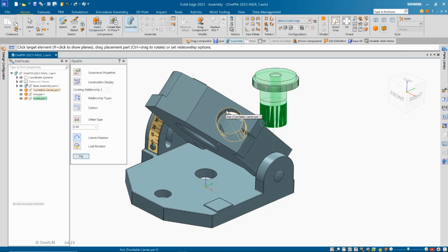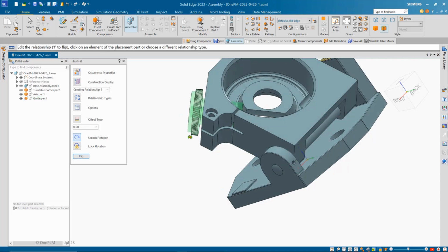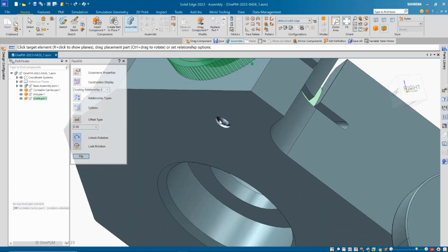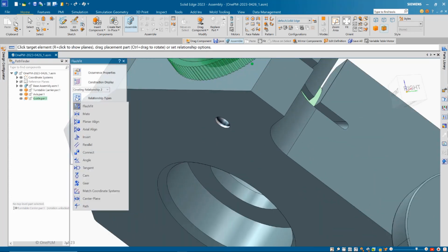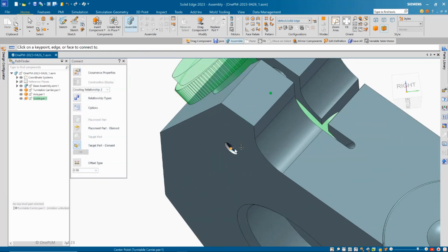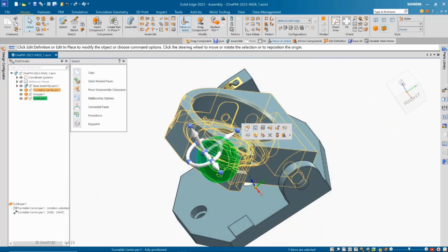Another one on here, we've got the guide, a simple one to start off with. It makes it much easier being able to drag that as well. This time we need to select the center of the torus. We need to select the center point to the axis. But again, during this we can't do this, but we can easily say, actually I want to do a connect. This allows a key point to connect to the center point of an axis. This makes sure that this is correct.